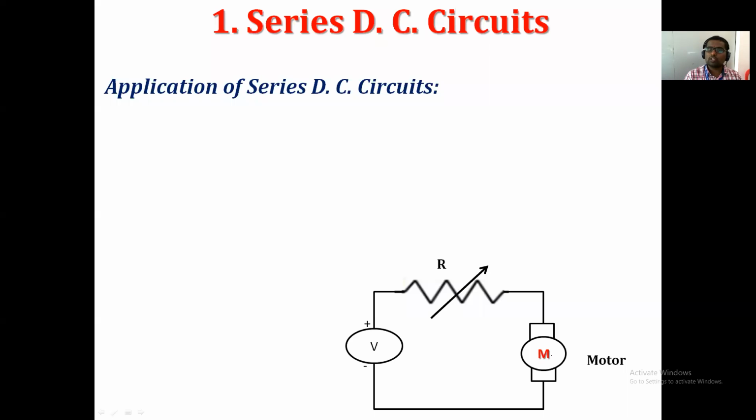आता त्या स्पीडवरती कंट्रोल करायचा आहे, म्हणजे कशावरती कंट्रोल करायचा आहे? करंटवरती कंट्रोल करायचा आहे. जसं की आपल्या घरामध्ये आपण फॅन वापरतो, त्या फॅनसाठी एक रेग्युलेटर आहे, तो रेग्युलेटर म्हणजेच एक पोटेन्शियोमीटर आहे. तो जर ओपन करून बघितला तर तोच हा व्हेरिएबल रेजिस्टर आहे. म्हणजे आपण तो रेग्युलेटर 1 वरती केला तर फॅनचं स्पीड मिनिमम असतंय, 2 वरती केला तर फॅनचं स्पीड इन्क्रीज होतंय, 3 वरती केला की अजून थोडं इन्क्रीज होतंय. इज इट राईट? म्हणजे त्याला सप्लाय होणारा करंट आपण सिरीज रेजिस्टरच्या माध्यमातून कंट्रोल करतोय.